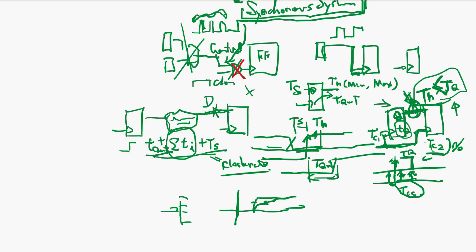But depending on the circuit characteristic, it could be a little bit higher or a little bit lower, and there is a certain clock timing skew here. So one clock drives only 3 gates, another clock drives 30 gates. The signal is going to be different. It looks like this, this guy looks like this. The clock timing skew gets even worse.